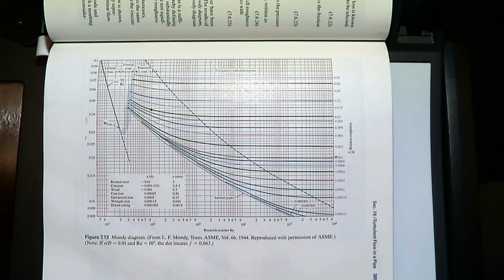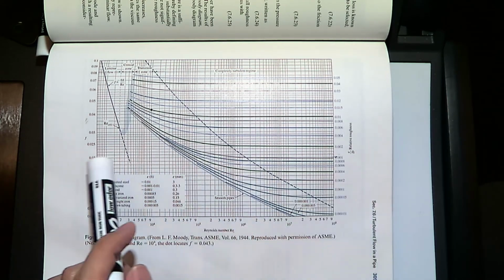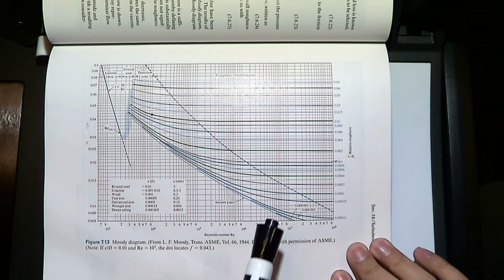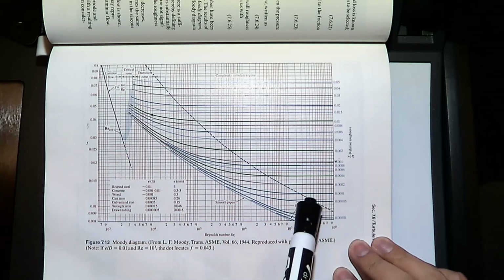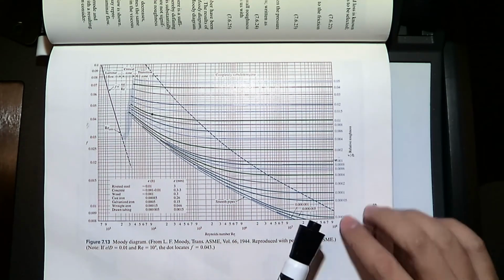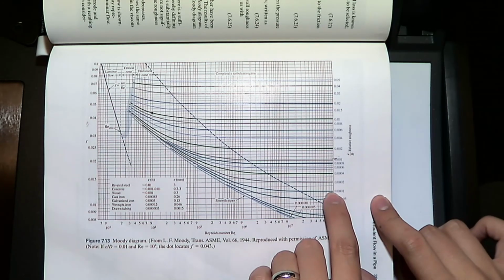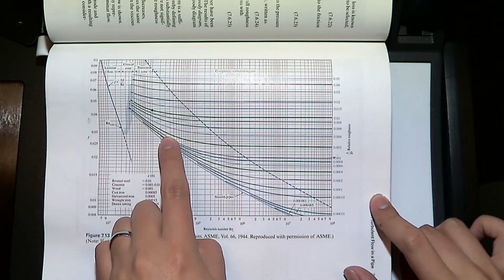And how does this help us? Well, using Moody's diagram, which is pretty much the industry standard, if I know the Reynolds number for my flow, and I know the relative roughness for my flow, then I can determine or estimate the friction factor. Now, using it takes a little bit of work. What's important is these lines that you see here, these curved lines, represent similar relative roughnesses. In other words, this line where the relative roughness is 0.0001, throughout this line, the relative roughness will still be 0.0001, okay?